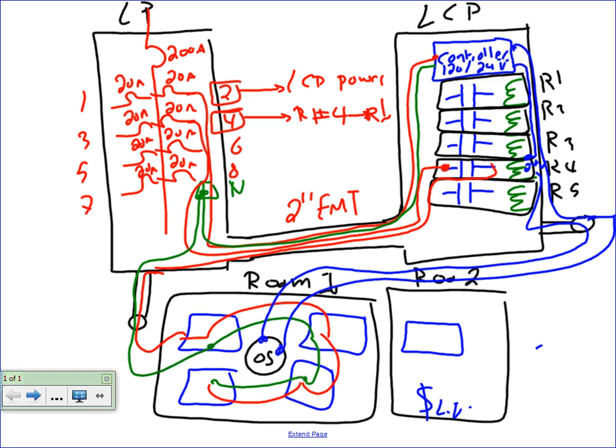And we add one more thing here: the occupancy sensor, the type of control in that room. Three things in a relay schedule: the circuit, the relay driven by the circuit, which area is controlled by this relay, and what's controlling this relay, the occupancy sensor, because it could be a low voltage switch.